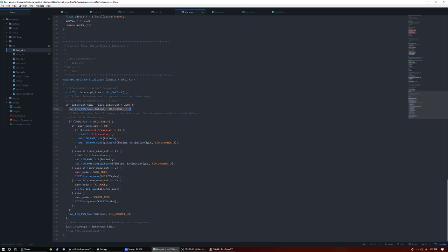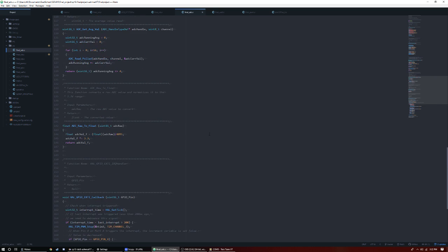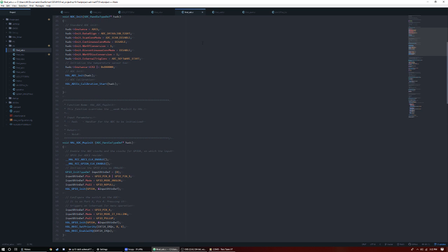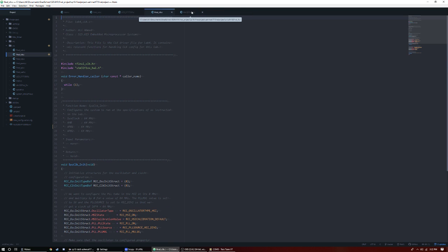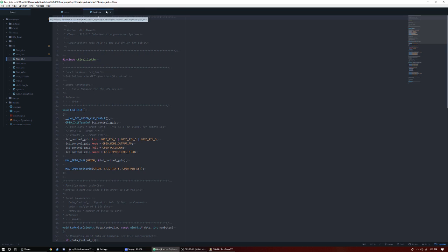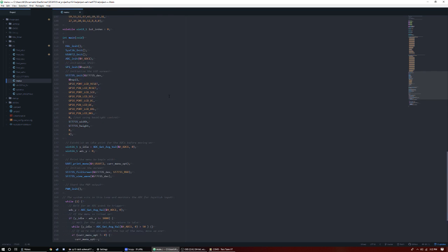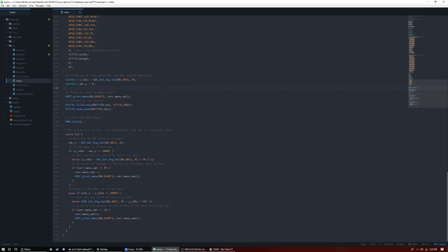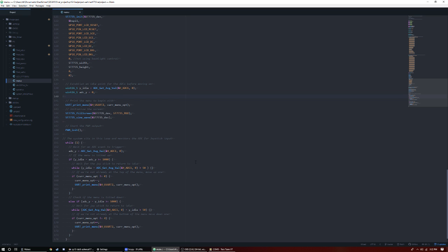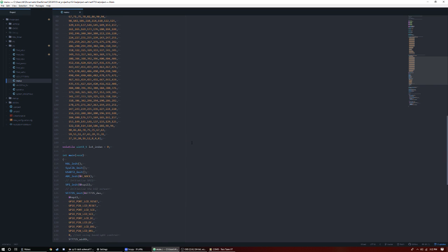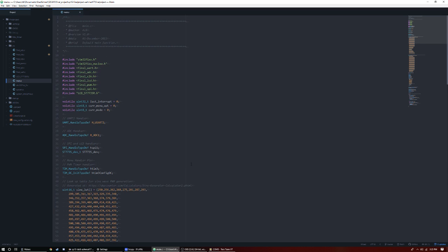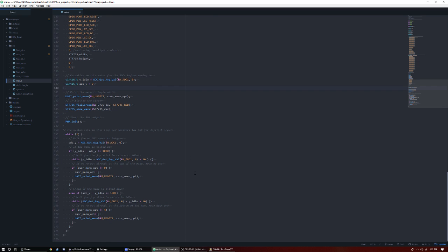That just ended up being the best answer for updating the LCD screen. I don't think there's actually a real good way of updating the LCD screen with the PWM still enabled, because a million times out of 1,000,001, it'll cause the LCD to enter a bad state. But yeah, that's about the gist of it.